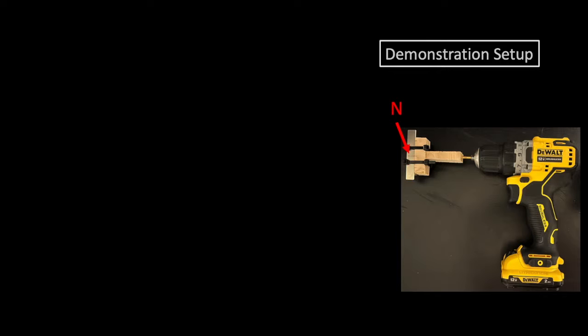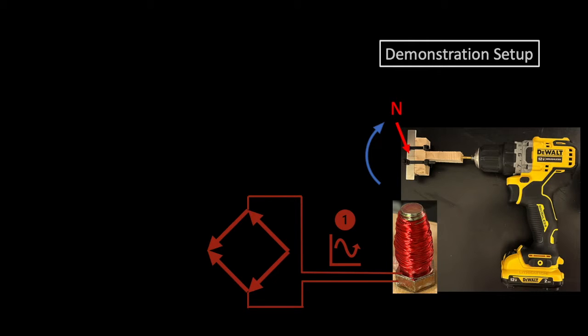The demonstration setup orients the permanent magnet vertically, and the rotation takes place next to a 400-turn coil of magnet wire around a steel bolt, which has a higher permeability than air. The resulting current in the wire will be alternating in a sinusoidal waveform, so a full wave rectifier circuit is applied. Since the resulting current is still a waveform, a capacitor is included to dampen the fluctuations.